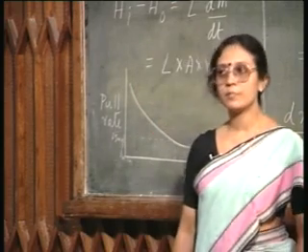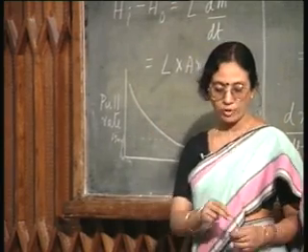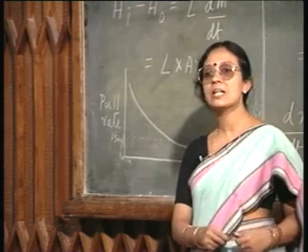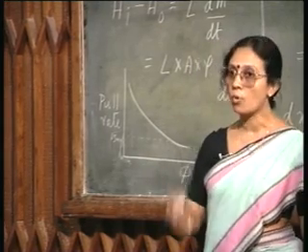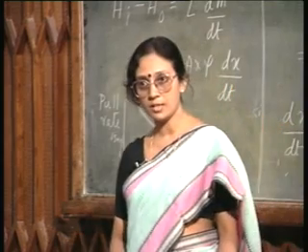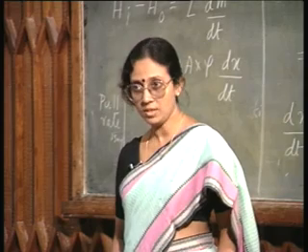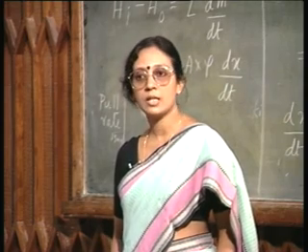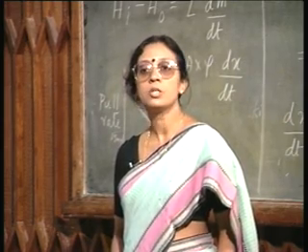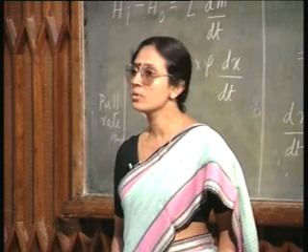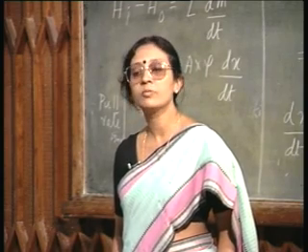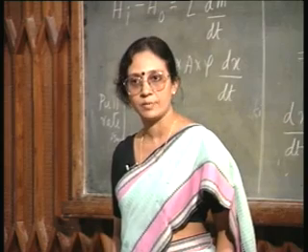Now, the point I am trying to make is this. Therefore, you see it is relatively easier to grow a smaller diameter single crystal with very low defect density, isn't it? Because for a smaller diameter crystal, we can afford to use a large pull rate, and when you use a large pull rate, the problem of this dislocation forming is less severe.